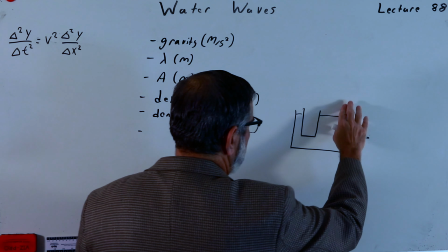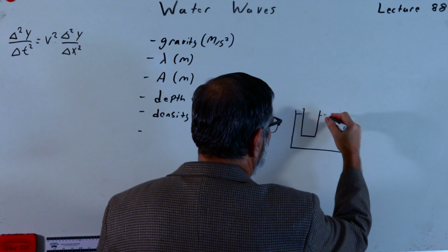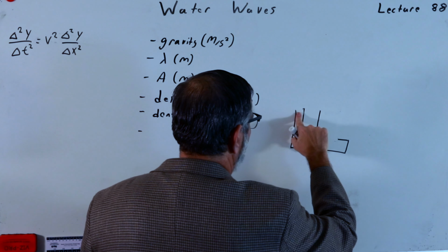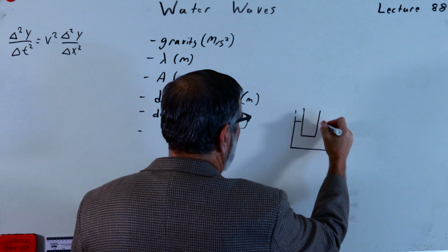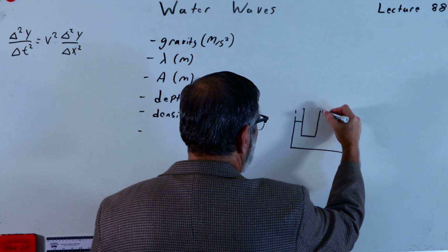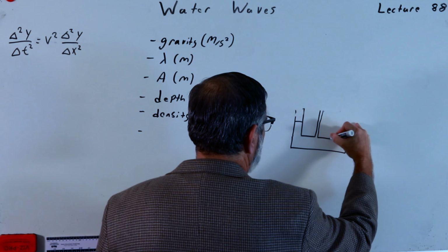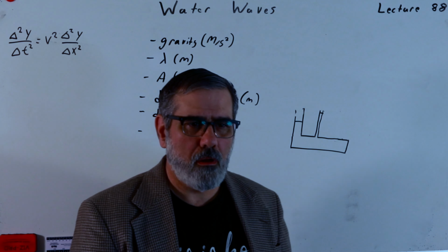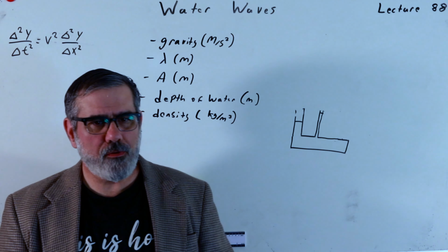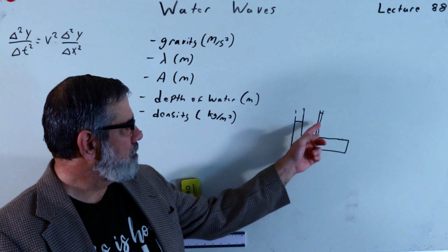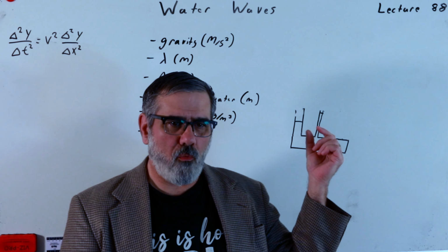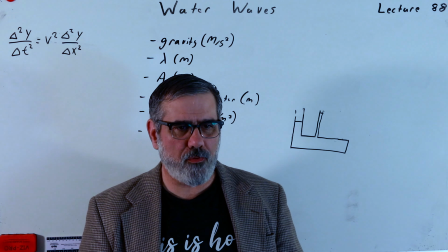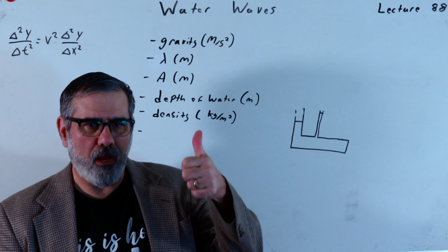Yes. Well, if I make this tube small enough, let me lower the level here a little bit. Let's say normally it would be here, but I allow this tube to be really narrow, right? It's a really narrow tube. You'll find that the water is actually higher in that tube. And the reason why is because of the surface tension component, okay? Because the little element of weight of the water there is small enough that its surface tension is enough to resist gravity and pull it up, okay?